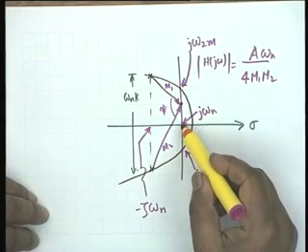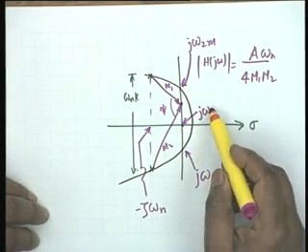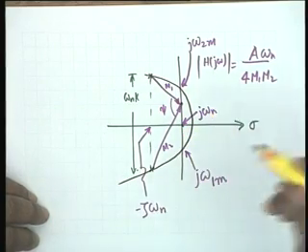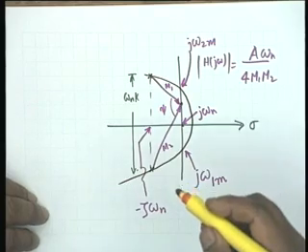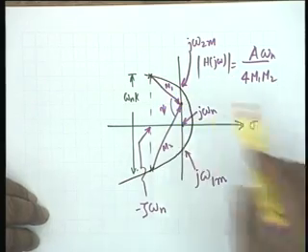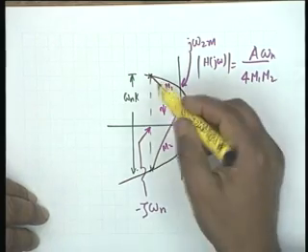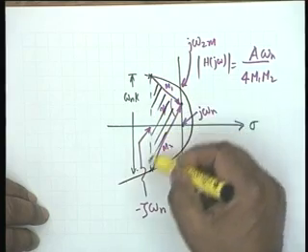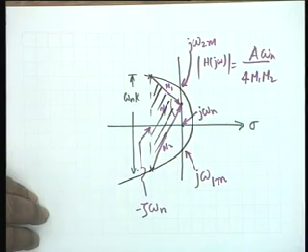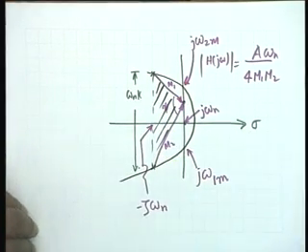Sigma equal to 0 here. This is perfectly all right. But this point is 0 j omega n. Now, the area of this triangle, let me show this. We can calculate the area of this triangle in two manners, exactly like in the single tuned circuit.